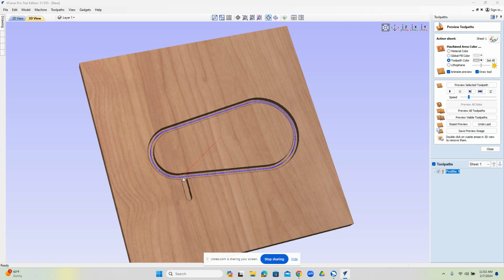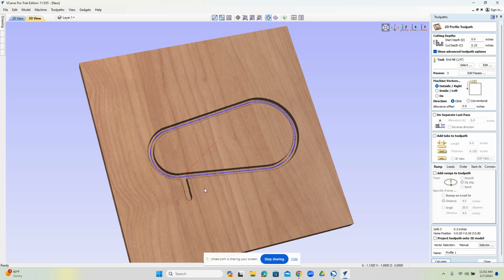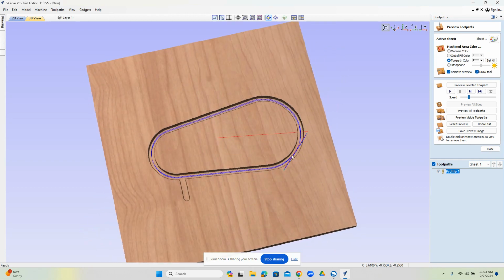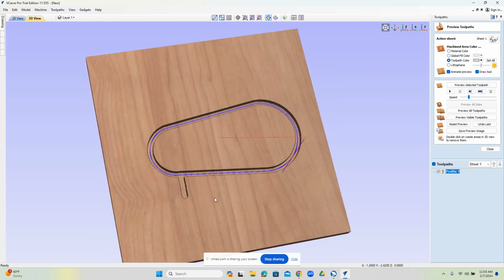So, you know, we could come in this way, come around the part, and then radius out. That's kind of the lead approach that I would like. So let me see if I can do that. Let's see if we can change our corner. Move it to here and calculate. All right, so now we moved it over to here, and I think that actually looks a lot better. This type of lead in, you know, we plunge in off the part, we come in, we're going to go around, and then as we come out, one of these straight type methods on a circle.